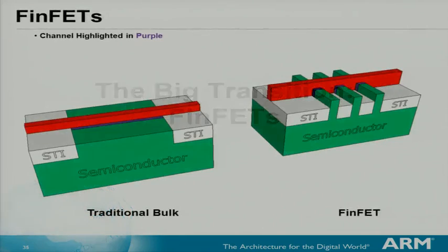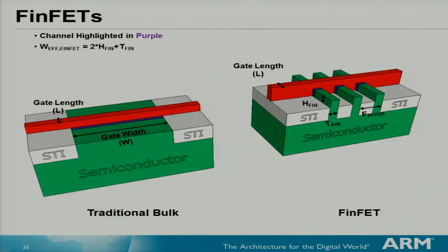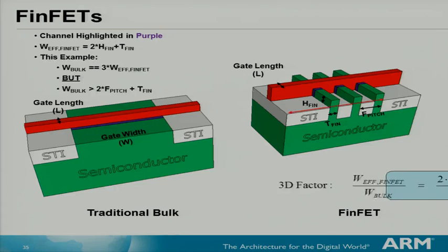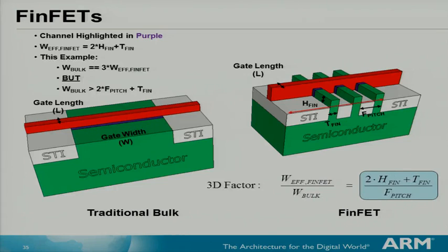So now we come to the big transition, that's FinFETs. I'm pretty sure everyone here is familiar with FinFETs, but the big difference to designers is instead of having a variable gate width where you can vary it by any number, your gate width can only be changed in number of fins. So you can have a single fin, 2 fins, 3 fins, but it's an integer multiple of the fins. So you cannot have an arbitrary gate width value.